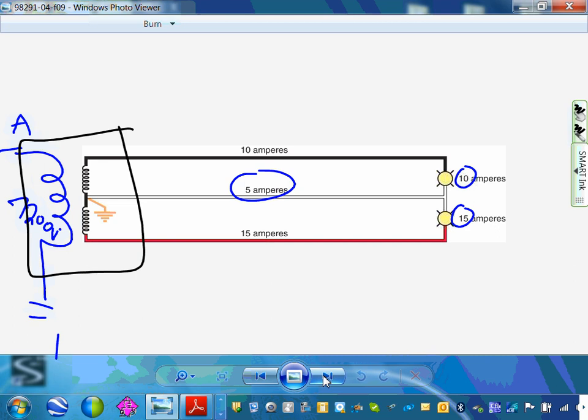It drove me nuts the first time I saw it in the US. Nuts. Is this single phase or three phase? What the heck is this system? It's a split-phase system. One phase, here's phase A. Can you see it coming from the utility? They split it into two hots. You would never go astray again if you understand it this way. One phase split into two with a neutral.